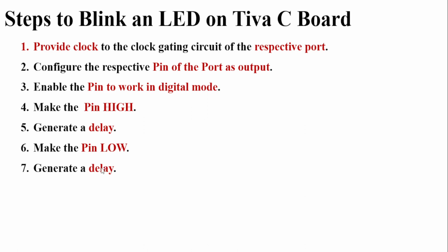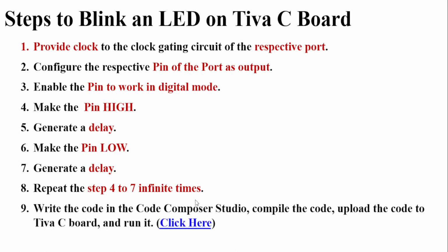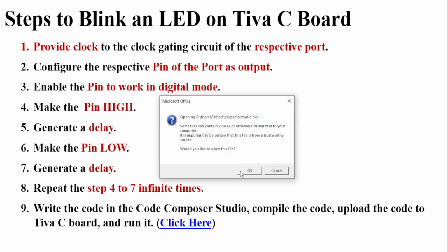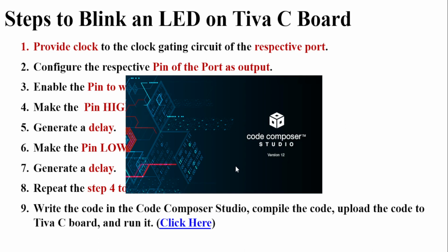So in this way, if we keep on repeating the step number 4 to 7, that is making it high, delay, low, delay, then again high, delay, low, delay for infinite time, then in that case the LED will be blinking for infinite time period. So let us try to write a code to meet all the requirements of step 1 to 8 in the Code Composer Studio IDE. Let's go to the Code Composer Studio.